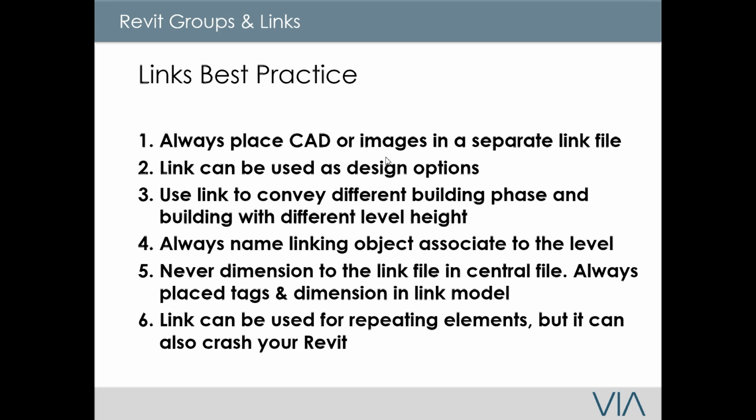Always name links for objects associated to a level. If you're using a link for repetitive elements, I always recommend people name the links the same as the level they're hosted on. The reason being, later on I will demonstrate in the file, opening up one of the Revit projects, that you will see how many links are in there, plus where the level is located.